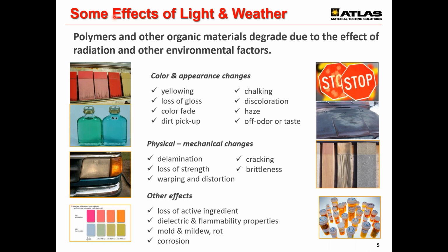But also polymers consist of many additives. Flame retardants, herbicides, fungicides are added to a polymer to provide protection for the polymer. And those additives actually can degrade. You don't see it. Maybe the mechanical properties do not change, but the properties in general of the polymers, of the coating, can change.